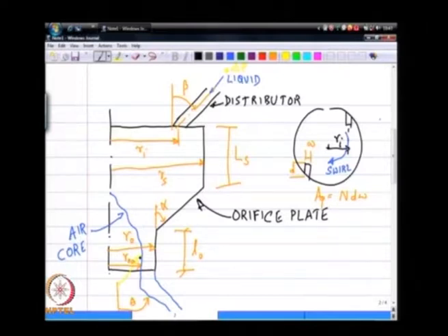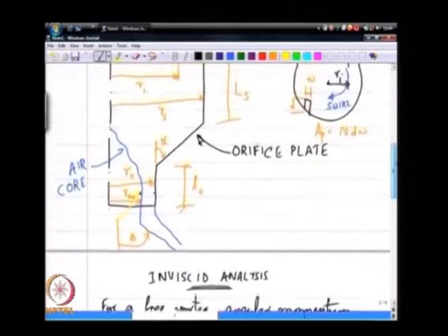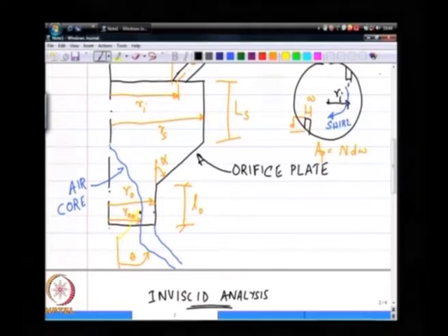I can also apply it from that same tank to another point, let us say here or here, does not matter, but if all the streamlines are originating from the same tank, I can apply this Bernoulli's equation between any point inside this swirl chamber and the tank, okay, which also means since the tank is at a constant supply pressure delta P, it also means I can essentially apply Bernoulli's equation between any 2 points inside the swirl chamber even if they are not on the same streamline,